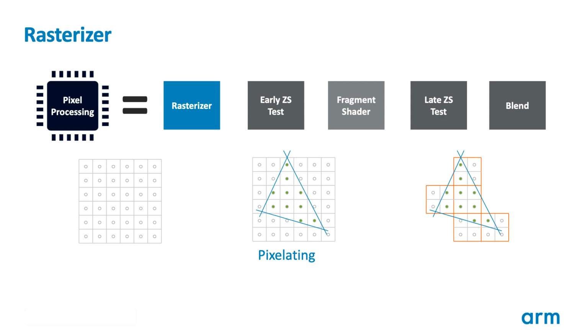One important thing to note with rasterization is that the output it generates are 2x2 fragment patches called quads. Quads form the dispatch granularity for fragment shading, the 4 fragments combining to provide the spatial coverage needed to generate the derivatives needed for MIP mapping and anisotropic filtering. Small triangles which only hit a subset of the sample points inside a quad will simply run the fragment shader with idle lanes in the hardware, reducing the shader execution efficiency. In the left-hand diagram, we can see a small triangle which covers 10 pixels, but due to partial coverage of quads, it is consuming 20 pixels worth of the fragment shading capacity.